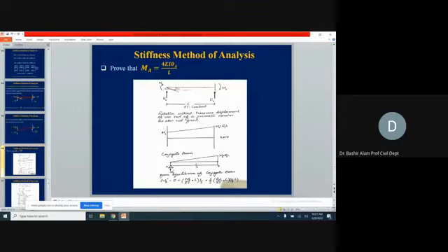This gives the load of this rectangle, and we take the moment about A. The moment arm is L divided by 2, because its resultant acts through the center. So MA L over EI times L by 2 is the moment of this rectangle about point A.